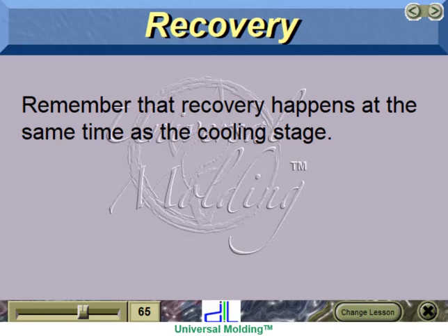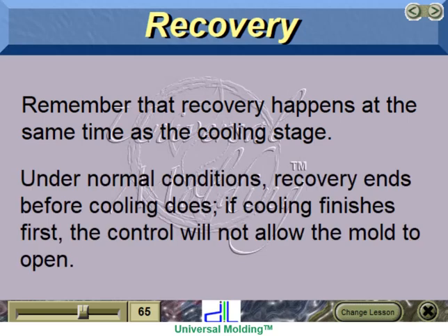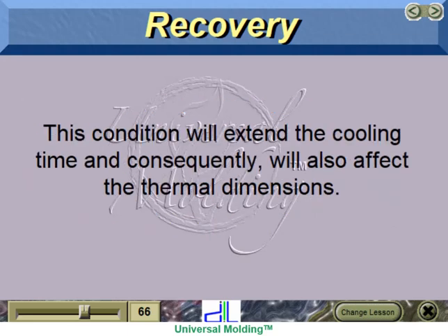Remember that recovery happens at the same time as the cooling stage. Under normal conditions, recovery ends before cooling does. If cooling finishes first, the control will not allow the mold to open. This condition will extend the cooling time and consequently will also affect the thermal dimensions.